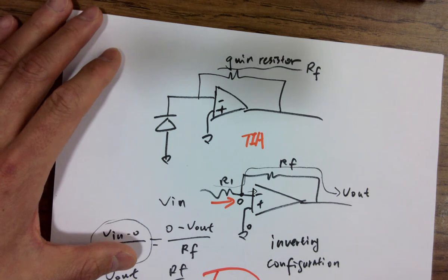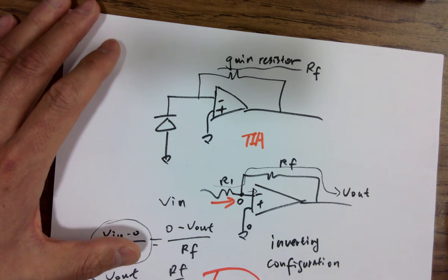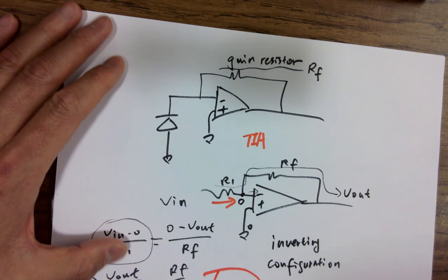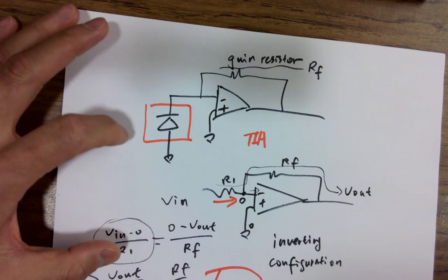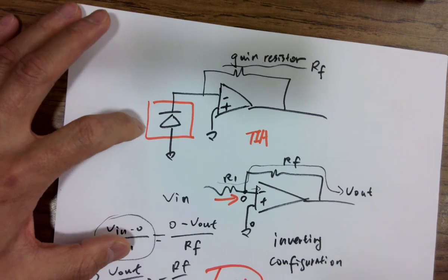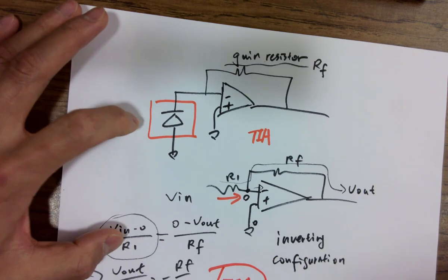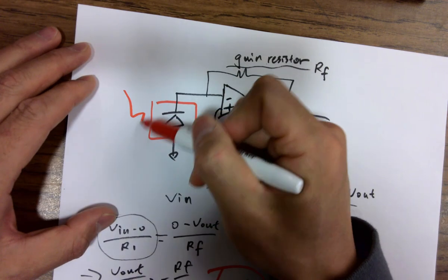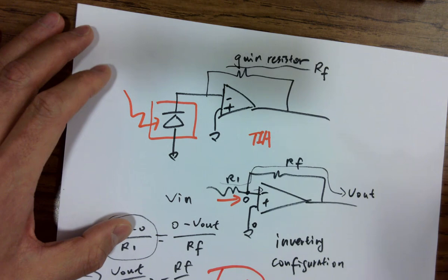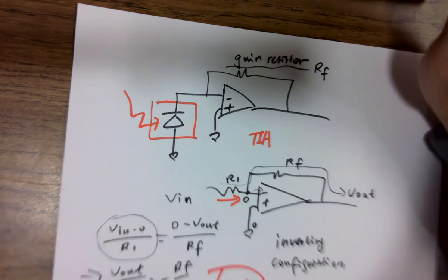So if you think about the pixels, the cameras in your phone or everywhere, any digital pixels. This is a little pixel. It's a photodiode. If you are in digital VLSI, you can lay out a little diode. In silicon, if you lay out the diode and reverse bias it, whenever it receives light, it just needs to be a regular diode. It's really amazing.